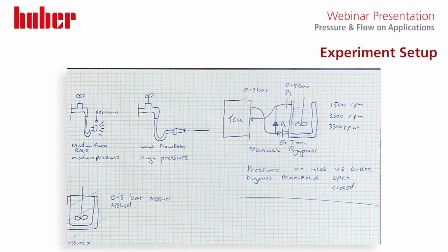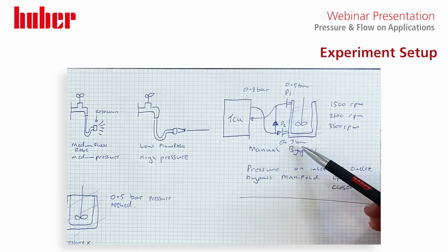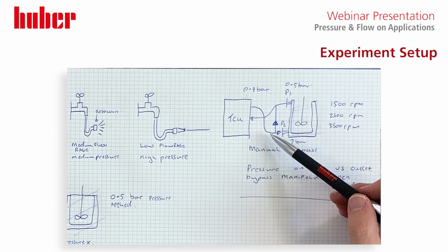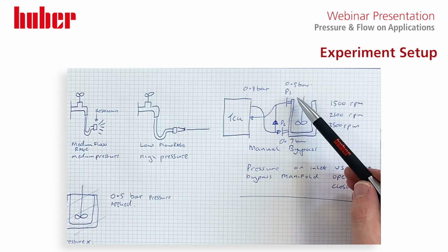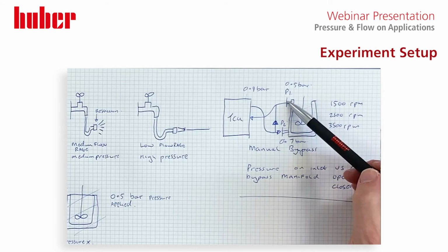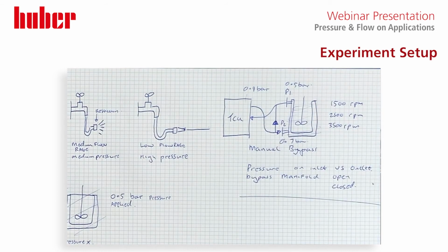In our case with our Chili, the main reason for our pressure drop on our inlet is the fact we've got an inline flow meter, which is disturbing the flow and causing a pressure drop. Then we have our drop across the jacket and then back to the TCU.